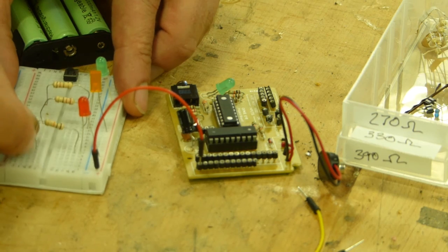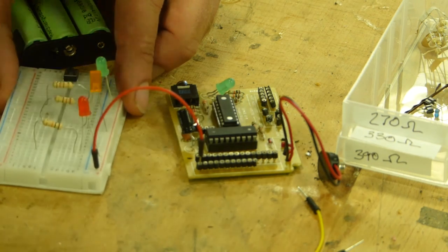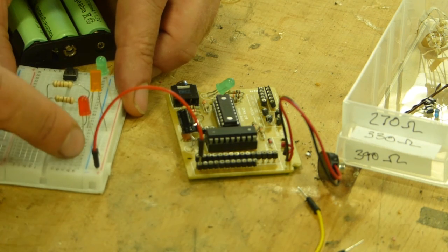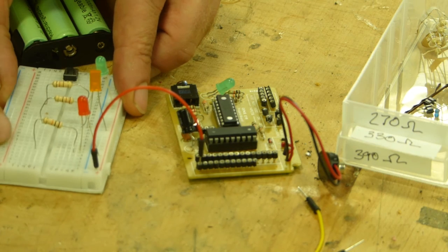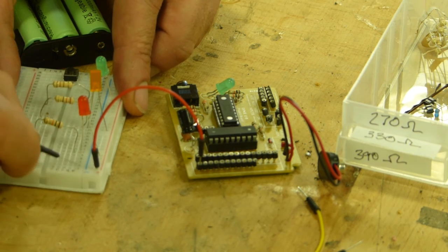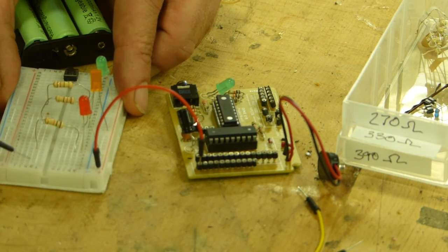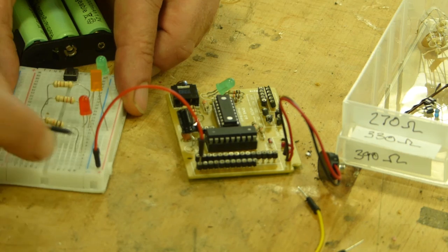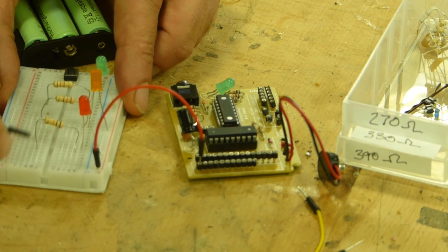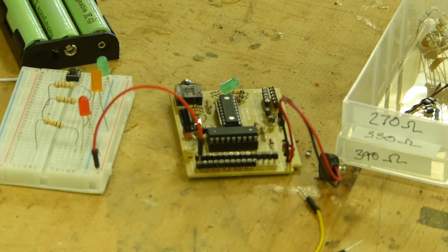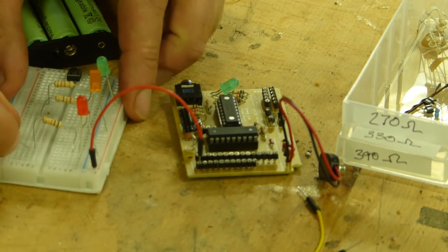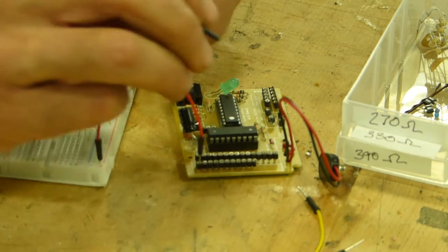Now in that same column is that resistor, that 330 ohm resistor. That is straddling across to the next column. Now these columns are independent from one another, so that one isn't connected to that one, which means we've now got a connection to there, join there, and a connection to there. And all I need to do is finish that off with another wire, which I'll put in like that, to Q0,